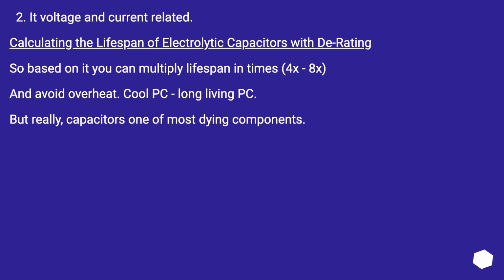Voltage and current related. Calculating the lifespan of electrolytic capacitors with derating. So based on it you can multiply lifespan 4x, 8x, and avoid overheat. Cool PC, long living PC. But really, capacitor is one of the most dying components.